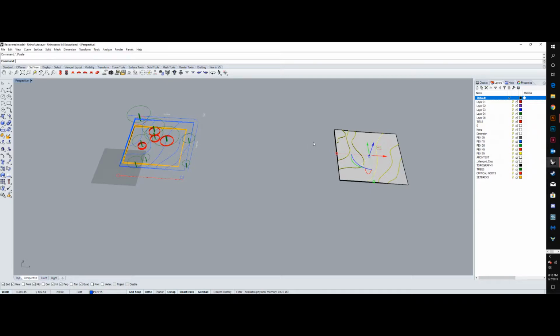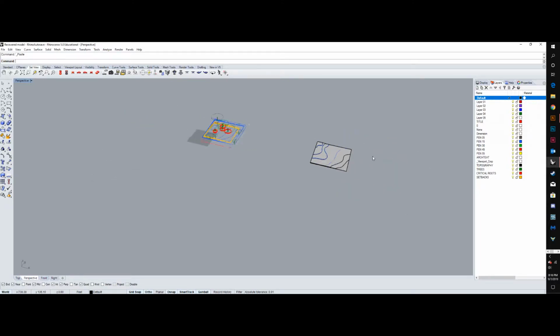Whenever you realize you moved something without copying it first, you can always continue to place it, then copy it, Control Z to move it back, and then Control V to place it where you wanted it. It's a weird little dance, but it's a common maneuver you're going to have to do over and over again whenever you make mistakes, and they'll happen.